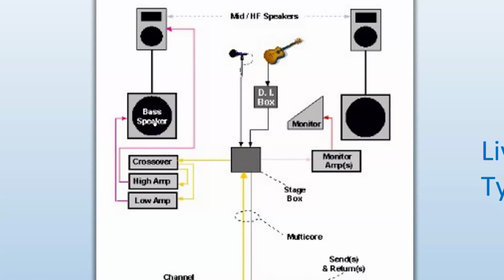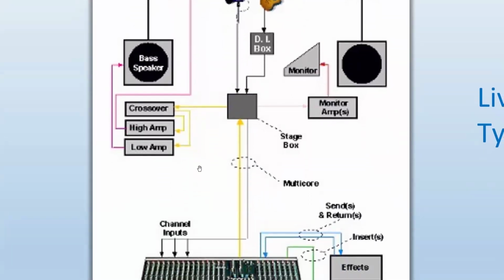So if you have 4 ohms impedance of the speaker here, and an amplifier right here at the front of the house, of course you would have a thicker cable going in there, not just a thin cable, maybe 22 gauge wire for the signal because it's low power. The higher power will be maybe 12 gauge wire or something like that. Yes, it's going to give you less resistance, but it will still give you 2 or 3 ohms compared to 4 ohms. That is unacceptable because the losses would be just too much.